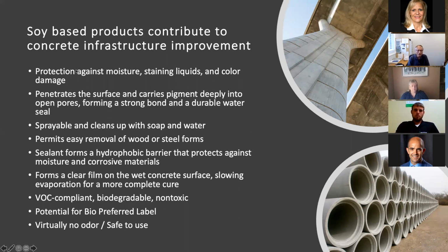As strong as it is, it's sprayable and cleans up with soap and water, so it's nice to use. It does provide a release agent for wood or steel forms. The hydrophobic barrier protects against moisture and corrosive materials, and the clear film on the wet concrete surface does slow down the evaporation, allowing the concrete to have a more complete cure.